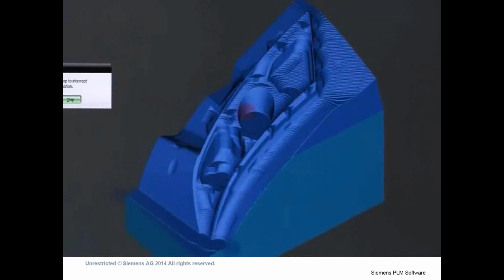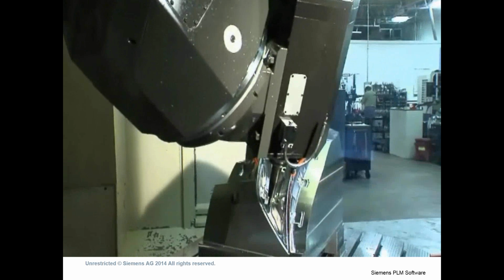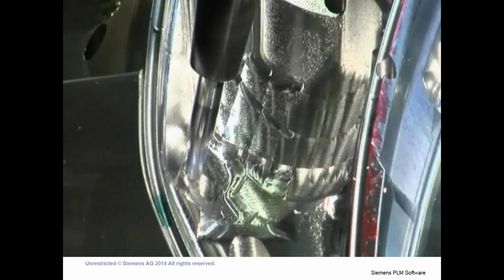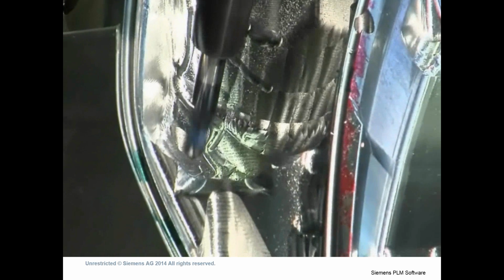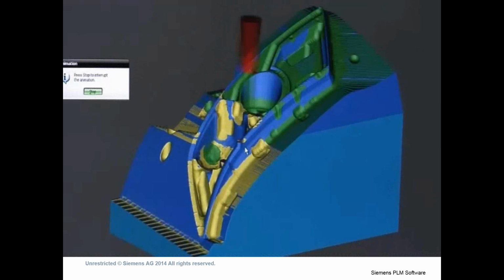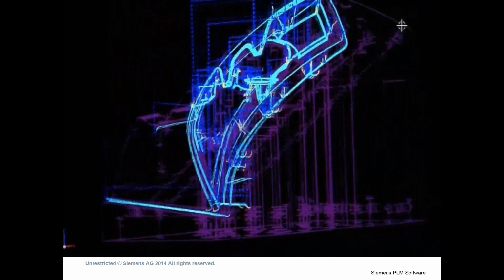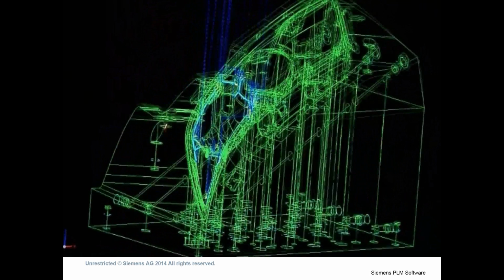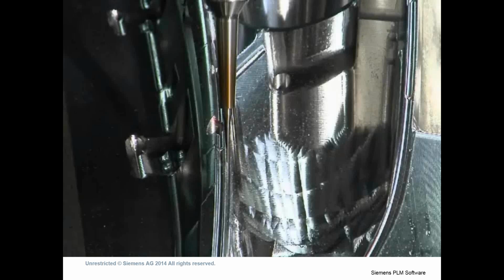You've got to save time, you've got to save money. So we implement high-speed machining whenever possible: small cuts, light cuts at fast feed rates. And yes, NX has several options that you can adjust your paths accordingly. There are options in NX that will actually turn the corners, which creates a much nicer and smoother path. It doesn't have the jerkiness of the machine. It's faster, it's better quality. Now you just set it up and away you go.